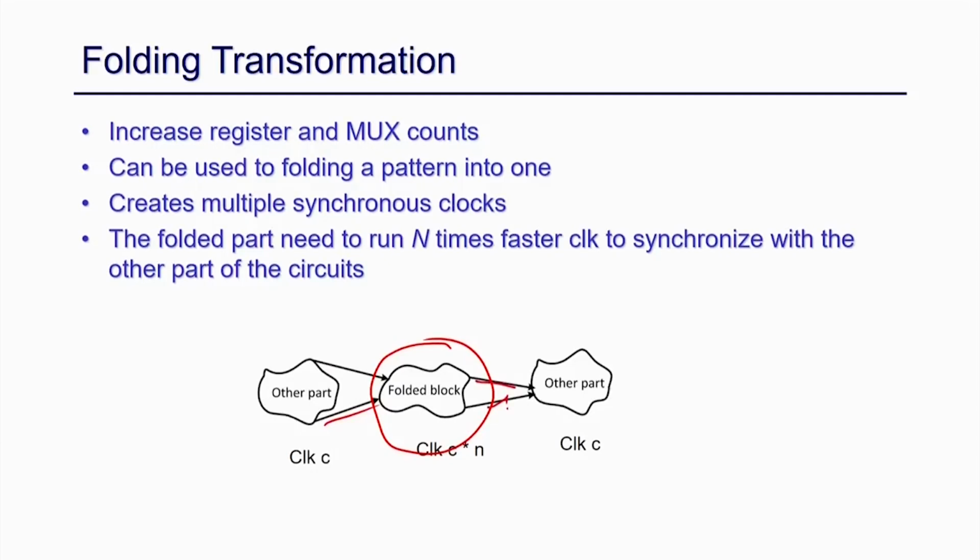So, if you want to run all these components in the same clock, you have to add some synchronization mechanism, so that the data that was expected after 1 clock will now wait for 4 clocks, because now your folding factor is 4. So, after 4 cycles only the data will be available. Similarly, the input may be fed in every clock, but now it has to hold the data for all 4 clock cycles, so that the operation can be executed here, right.